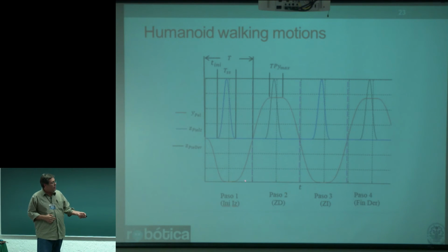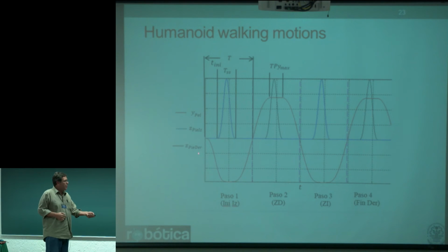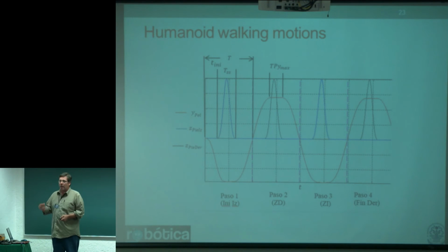So this is where the cycloidal forms came into the play, because we have to move here, then stay a little bit, and then go to the other side, etc. And for the height of the foot, we can lift it in the right moment. So these are parameterized trajectories. I am going to be able to tell how long the step will be taken and at which instant we'll be lifting the foot, etc. So this is for stability and rapidity and velocity issues.